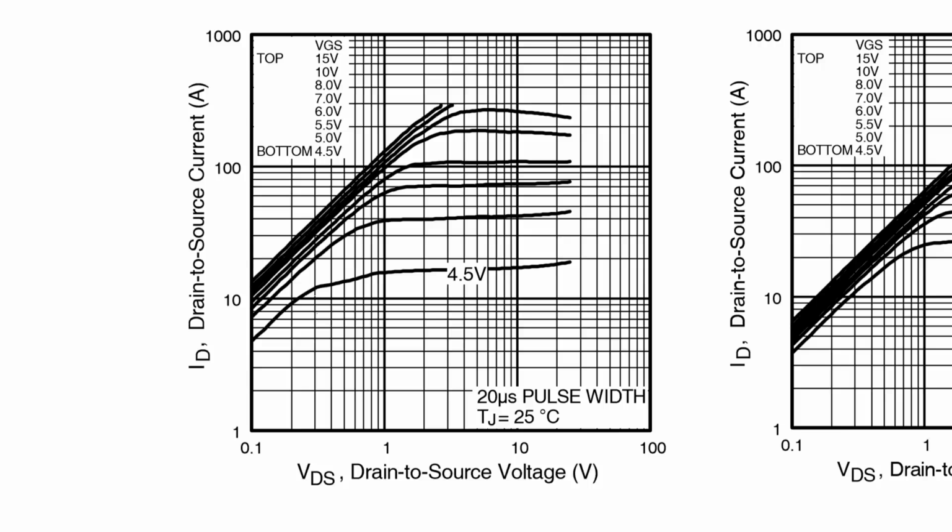Okay, so on this one, this is your voltage between the drain and the source. And if you remember the example that we had, on the high side of the load you had 12 volts, and on the other side you had ground. So the source voltage in our application was 0, and then the drain was whatever came through across that thing. So that's the voltage that we're looking at across the FET.